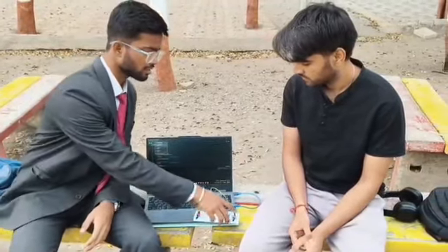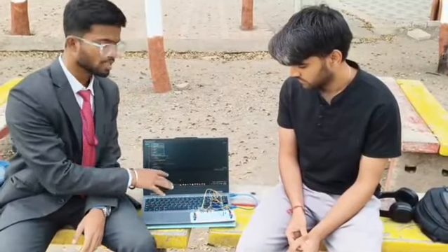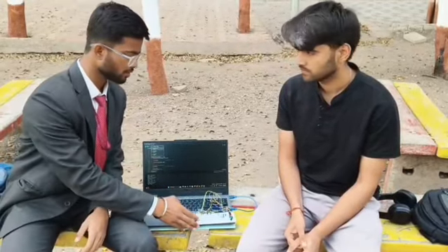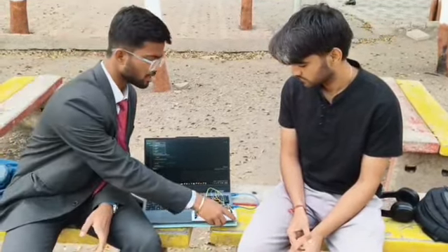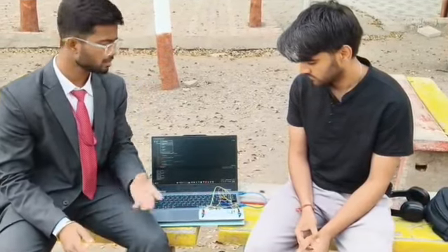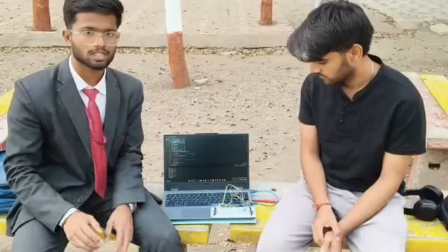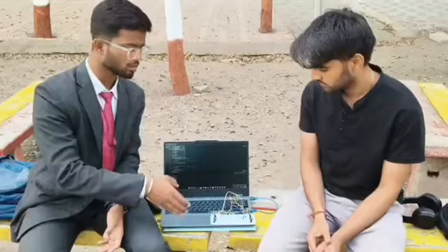This is the first IR sensor and this is the second IR sensor in the code we have written. When the first IR sensor detects the object in front of it, it starts the timer, and when the second IR sensor detects the moving object in front of it, it stops the timer. When some moving car or something like that passes through, the timer starts, and then the second IR sensor stops the timer. By this we have the formula, speed equals distance upon time, which helps to calculate the speed. With the help of it, we measure the speed of the moving object.